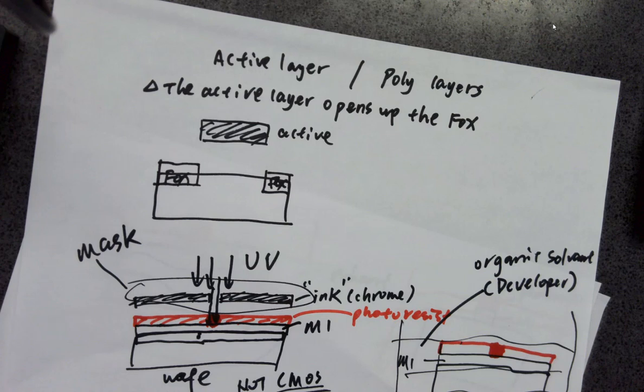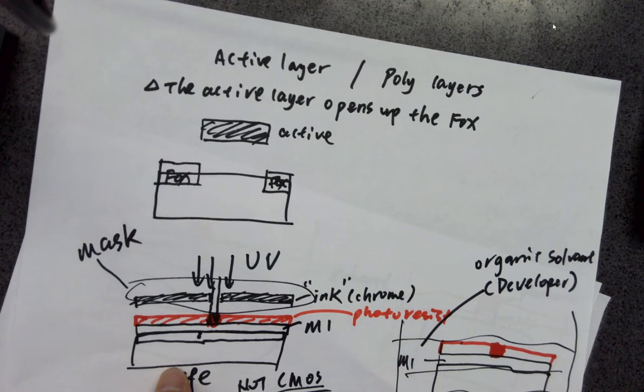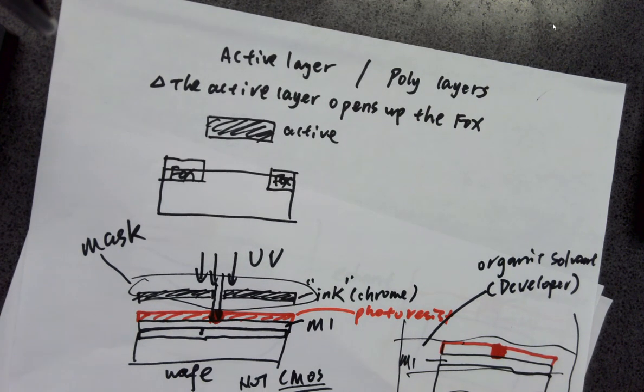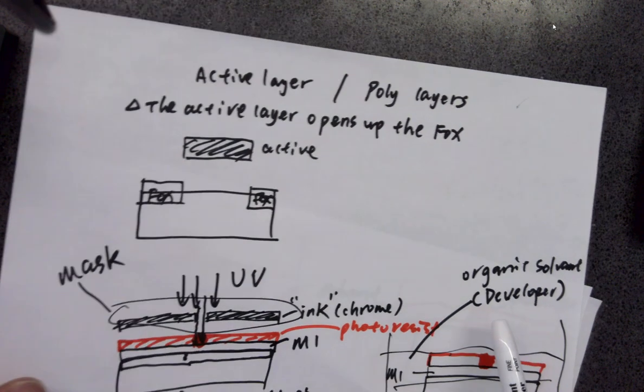So you guys are doing the layout, which is basically doing the masks. Just keep that in mind. The layout doesn't have any electrical properties. They're not even circuits, because the masks are not even circuits. You drew the schematic in either Electric VLSI or LTspice. So these are electrical circuits, right? Or netlists to make all the connections. But for Electric VLSI, when you are doing the layout, they are just shapes, just masks. These are not circuits. Keep that in mind.